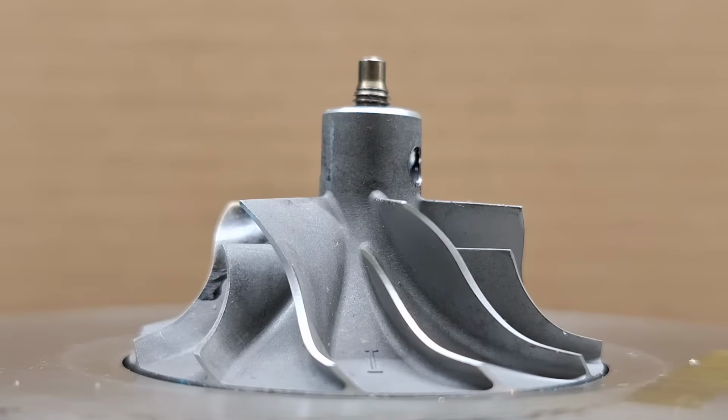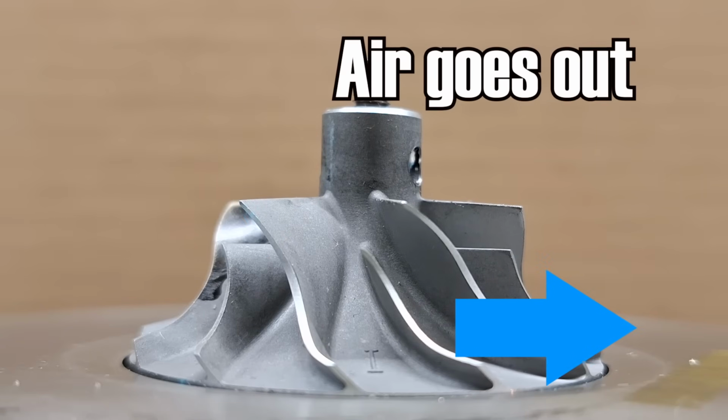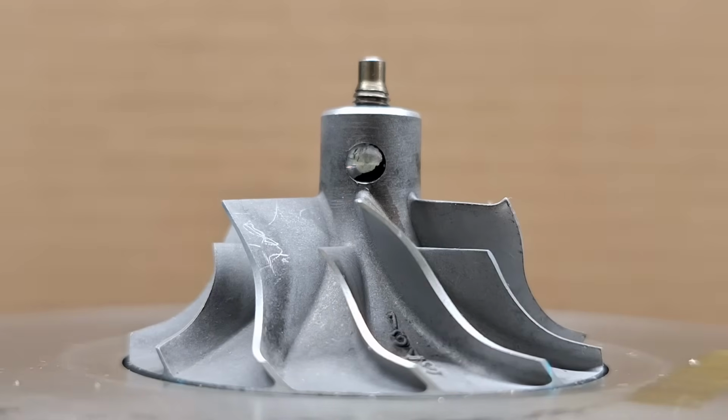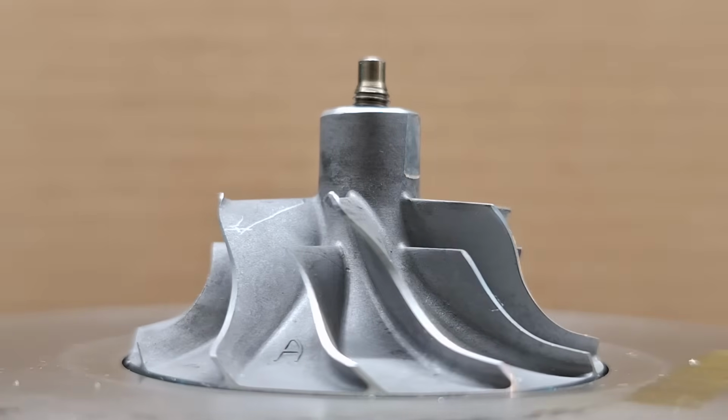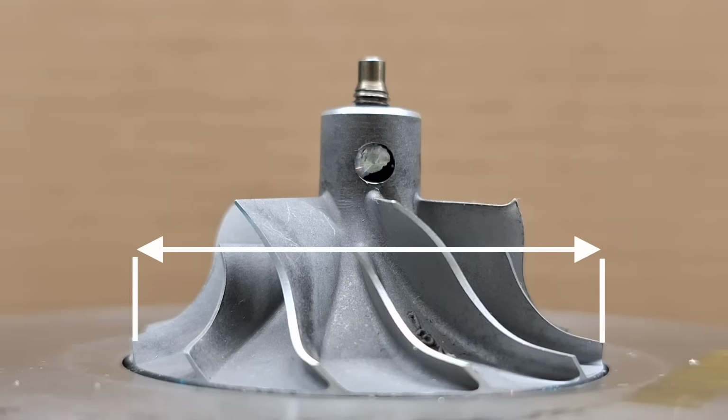On the compressor wheel, the air comes in through here and it exits through here. So that means that this is our inducer. This is the part of the compressor wheel that bites into the air. As the wheel rotates, the shape of the blades forces the air towards this lower part, which means that this is our exducer, or the part that spits out the air.